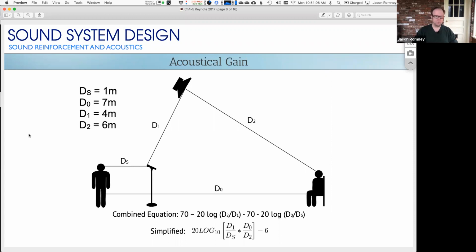No one cares whether the frequency response is awesome or not. They just want it to be louder. In that case, yeah, the EQ might be the way that you get through the day without people shouting at you. And you just have to accept the consequences of that: it's not going to sound very good, but at least it'll be loud and it won't be feeding back. But I would strongly advise you to not use that as your first line of defense. You can get much better results by especially just moving that mic closer to that talker.